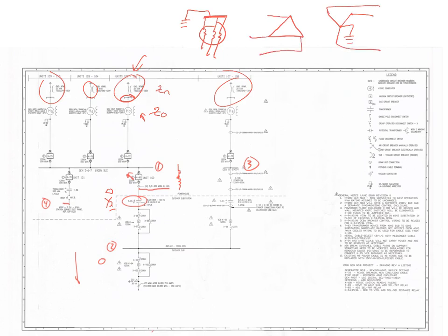Here's my 3-phase diagram. So in the delta, I'm not going to focus on the delta. I'm going to focus on the Y because it's usually easy to start. If I have 0 sequence current flowing in here, at least from the Y's perspective, is the 0 sequence current allowed to flow into the neutral? Sure, there's a connection here, right? So from the Y's perspective, yes, I can do that. What matters, though, is whatever, mantra time, whatever flows in the primary has to flow in the secondary, right?